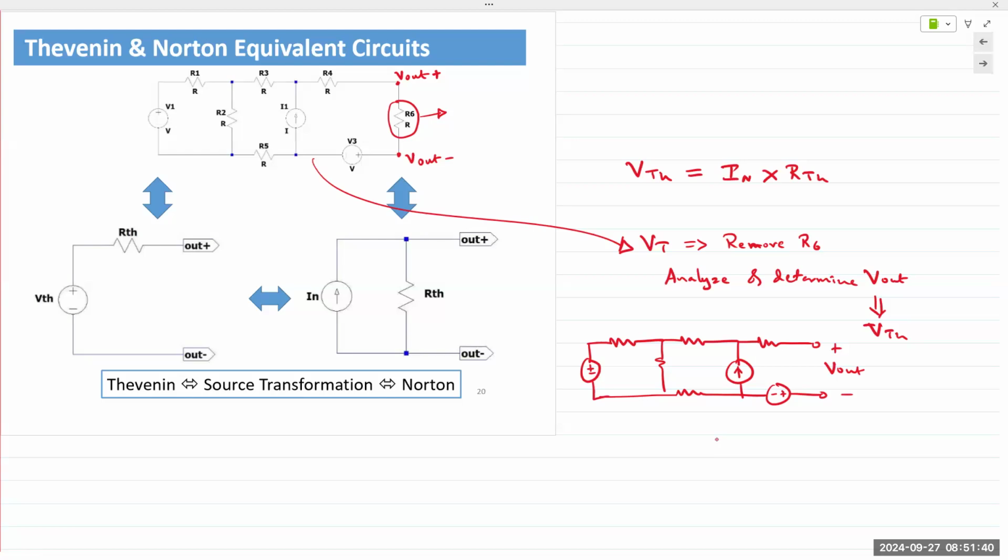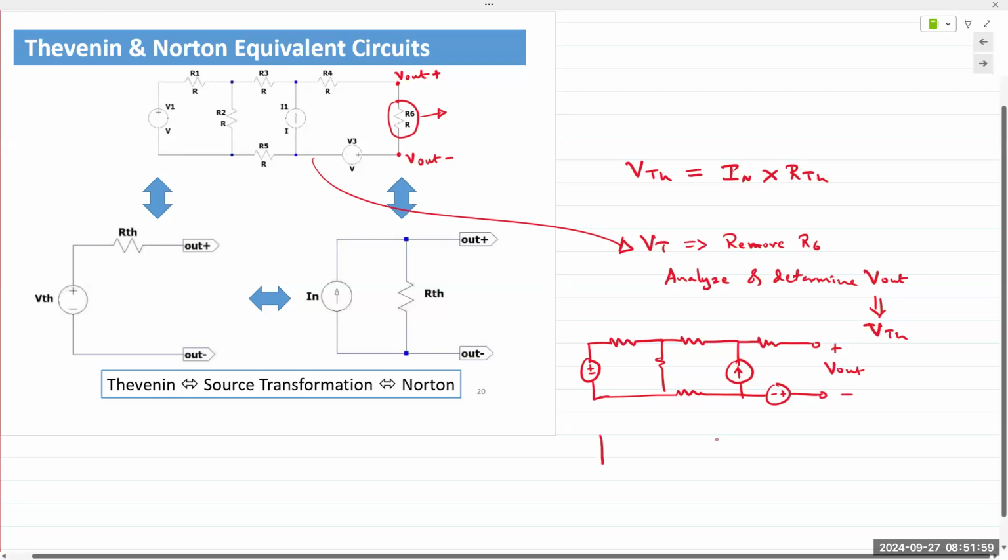Well, that is correct, but we do not short. The more accurate term would be that we turn off the voltage source, but we actually remove and replace the voltage sources with a short circuit. So yes, the answer is correct, but we don't short the voltage sources as much as replace them with a short circuit.